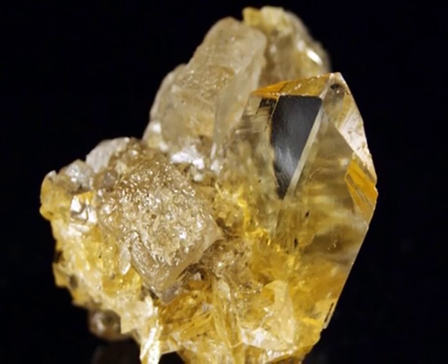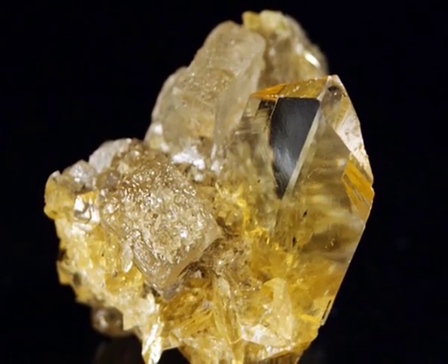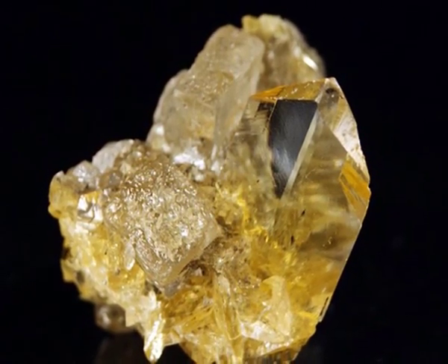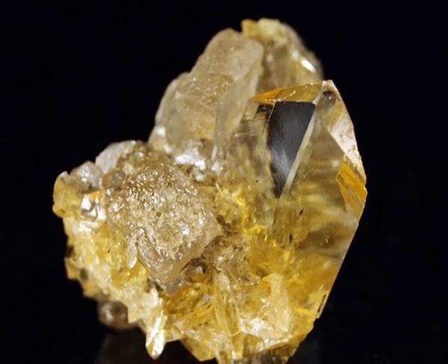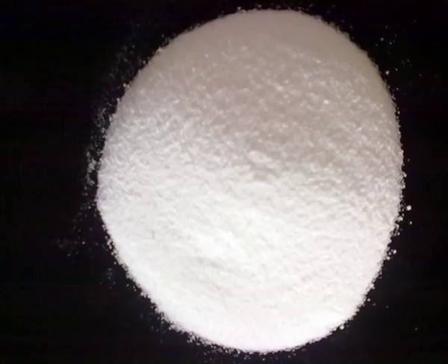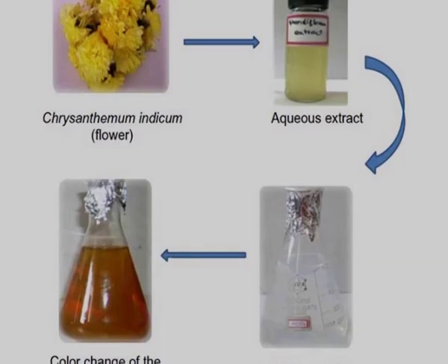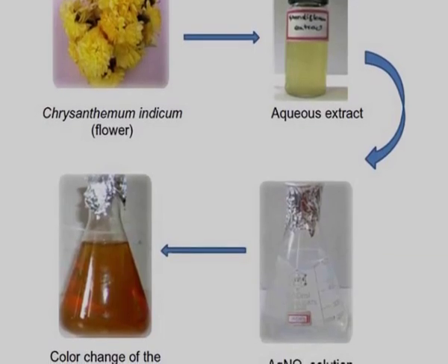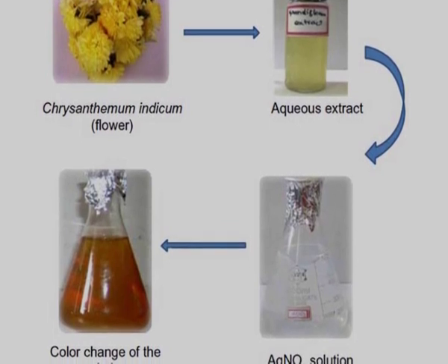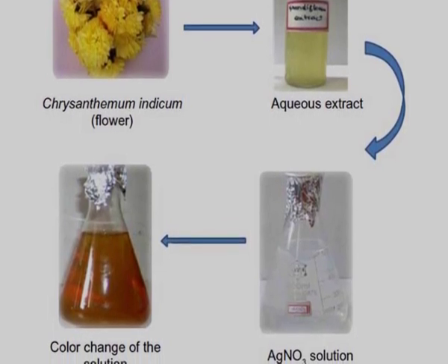Most papers today are neutral. Sulfates should be not more than 20 mg per kg of sample, and chloride can vary with the cleaning process of the pulp. The conductivity of the test piece can also be determined in the aqueous extract.